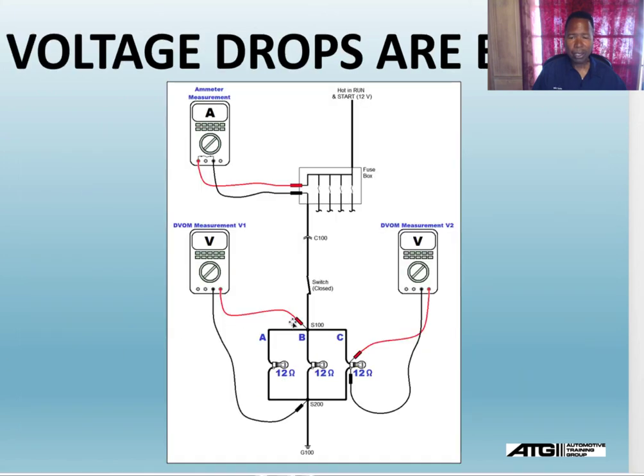But my voltage drops on the parallel legs, 1, 2, 3. Each leg will drop 12 volts in a parallel circuit. This is a parallel circuit. As long as there's no resistance in series to these 3 resistors, in series I mean up here anywhere, each leg will drop source voltage. My ammeter up here will see the total amount of current on this main line that needs to be fed for the total branches here.